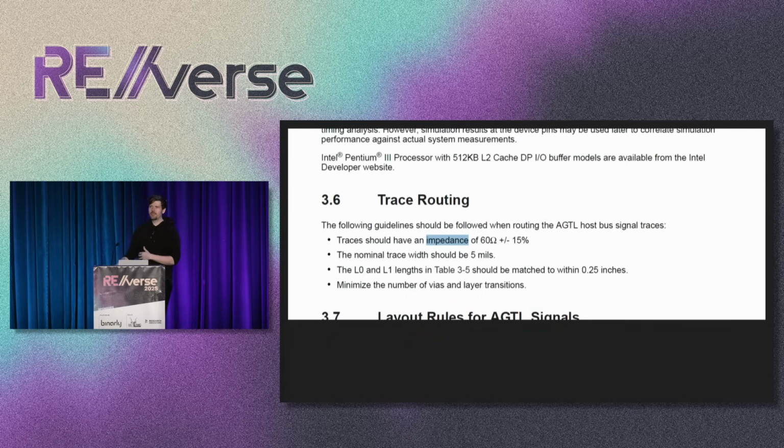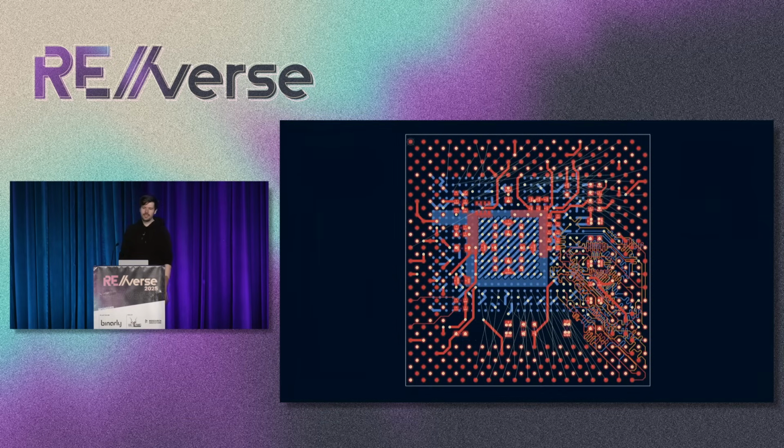To start building my own interposer, I was spending hundreds of hours reading all the Intel data sheets, which you can find for the old processors back in the day. Nowadays, all that stuff is super NDA'd, super proprietary. But Intel used to publish a lot of platform recommendations, motherboard design references and data sheets for their processors. So I started building this thing out. And this is going to be a 6-layer PCB. Most hobbyists normally have a 2-layer PCB, maybe 4, but we need 6 for this.